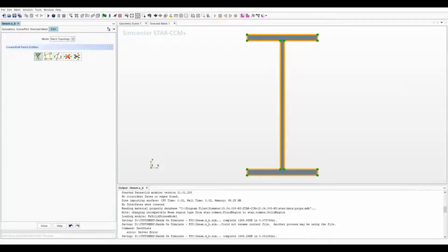So we have the corners highlighted now. The next option, so basically we would like to create a few more splits, and the scissor option on the screen, which you can see, is used to split the specified patch curve. So I'm going to use that and split the existing patch curve.